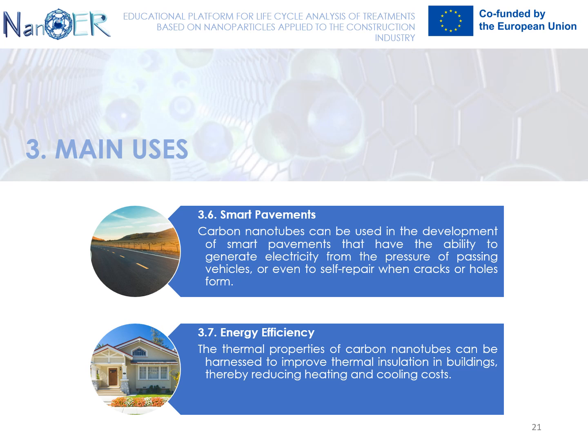The expanding needs of traffic data collectors lead to the exploration of new technologies and sensors for smart and functional uses. Self-sensitive CNT concrete is considered an effective sensor for traffic detection. The sensing ability of the CNT dispersed into the cement matrix detects the strain and stress which occurs in the pavement itself. Changes or deformations of the material cause changes in its electrical resistance, and therefore measurements of the electrical resistance can give information about the dynamic behavior of the pavement.